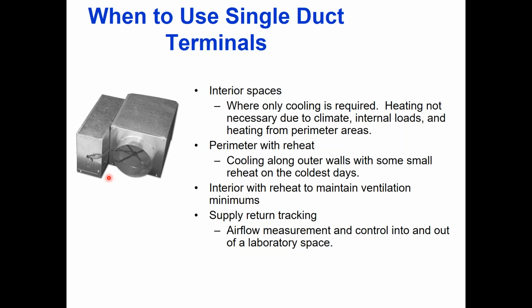Now, as a designer, don't automatically just default to putting heat on the interior zone, figuring out I'll cover my butt that way, because there's a pretty big price difference from going from a zone with no reheat to one with reheat. And the price difference is not in the form of buying the VAV box, because electric heaters are pretty cheap. The price difference is now you have to run high voltage power over to that guy, and it's labor. And then even more so if you have a hydronic-based system.